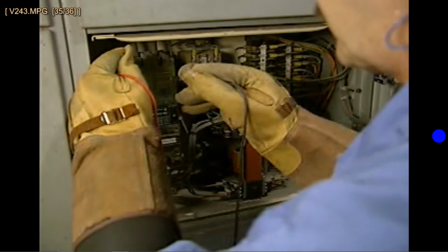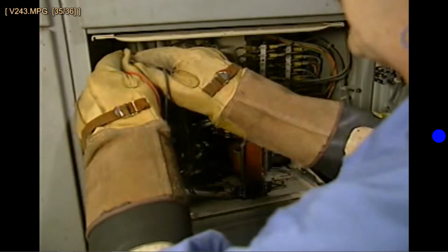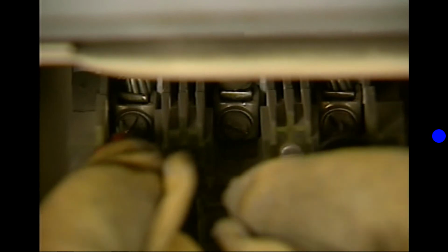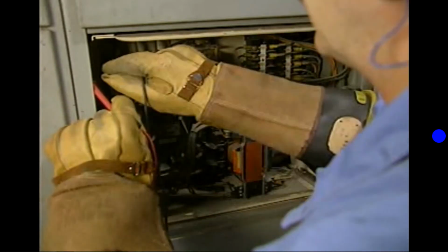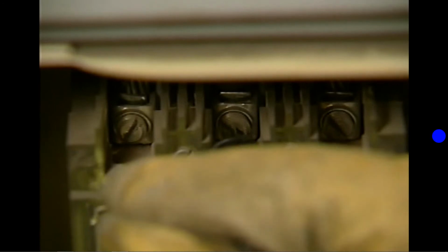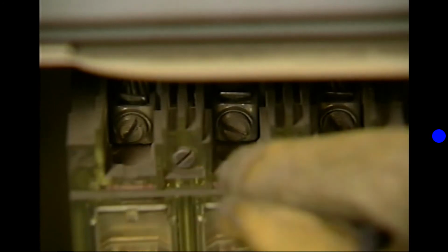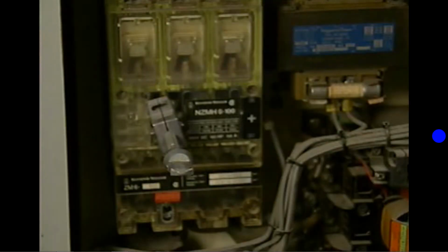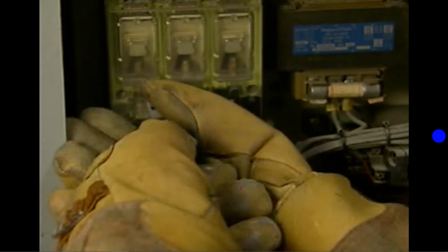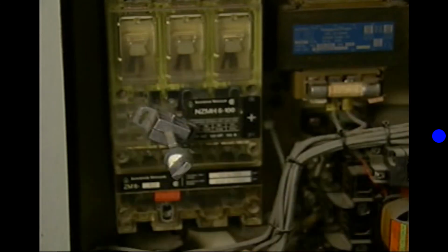If there is power available at the line side of the circuit breaker, then the wiring from the feeder breaker to the circuit breaker is in working condition. If there is no power, then the problem is in this wiring. In this case, the wiring would have to be inspected, tested, and, if necessary, replaced. If a visual check shows that the circuit breaker has tripped, the reason for the trip must be determined and corrected. Then the breaker can be reset and closed again so that voltage tests can be made.